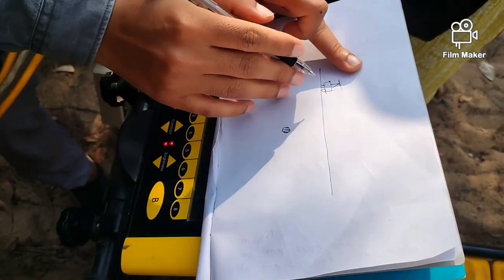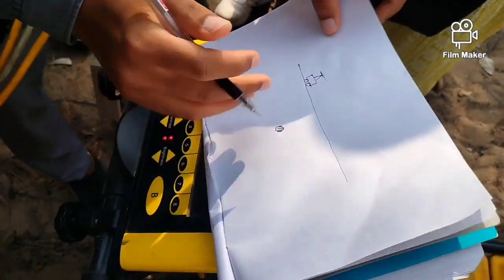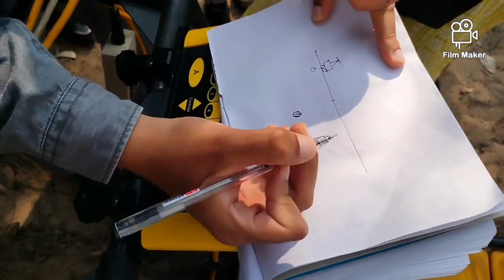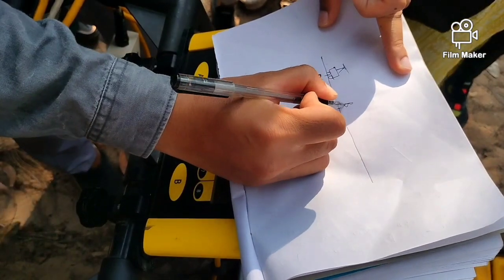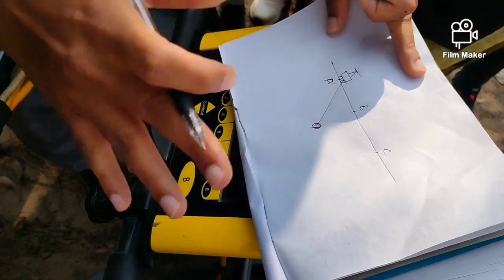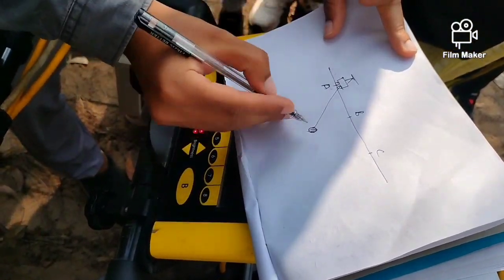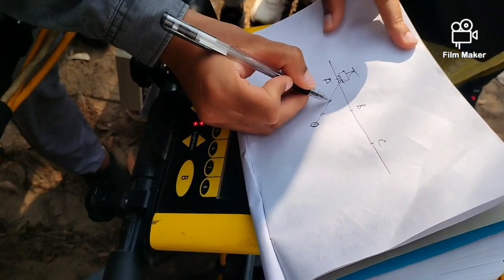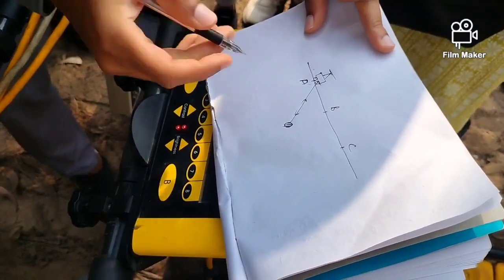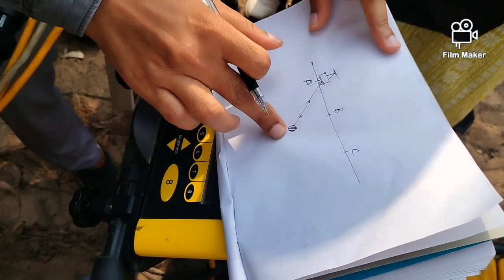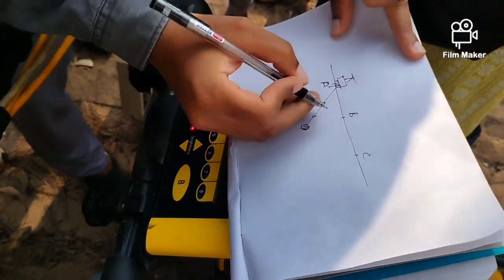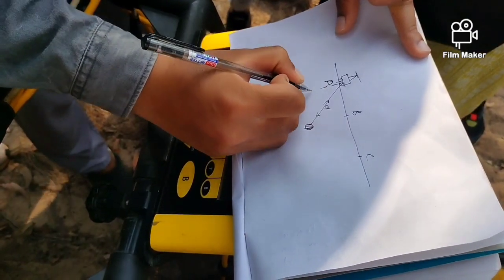Now the transmitter triggers down the pulse. So let's say at this point the GPR was at location 0, and these are locations A, B, C. When the transmitter triggers a pulse, it'll go in all directions, but since there are some utilities here, it'll go through this and then come back to this. But GPR never knows in which direction the signal is coming from. It just measures the time the signal went and came back. So GPR would tell you this signal is coming from some depth D.